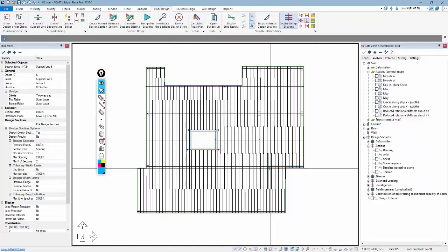Where we ended up last time, we talked about meeting the serviceability requirements of the slab, and that's necessary in order to determine what post-tensioning we need, what effective forces we have in our strands, and what the position of the strands are with respect to not only the depth of the slab but also in plane. All of those affect the strength calculations in the program. So before we go into determining the reinforcement requirements for not only service minimum reinforcement but strength, we have to get a good feel for, and hone in on, what the post-tensioning is going to be in the slab.